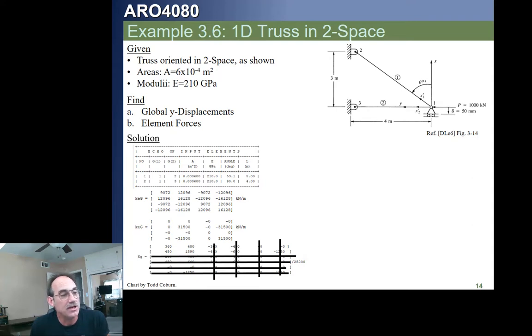Okay? Now what we want to do is get rid of this, because now you got to watch out for this particular problem. You'll notice that the sign convention of this problem is X in the vertical direction from node 1 and Y in the horizontal direction. That's a little tricky, and you got to be careful with that when you report your answers. That will throw you off if you don't notice that. Okay. With that said, what this means is this is free to move in the Y direction, the V direction, but it's given an enforced displacement in the X direction. That means our X displacement is 0.05 meters. Positive 0.05 meters. Oh, it looks like it's coming down, negative 0.05 meters, right?